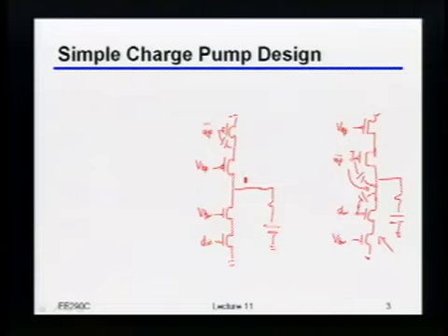The VGS keeps changing? Between what and what? Between the two cases. The up bar. Yeah, okay, so you're saying here we're changing the VGS of the current source device, whereas here we're changing just the VGS of the switch. Okay, that is true, although I don't think there's really a way around that because we have to turn things on and off. So somewhere something like a VGS is going to have to change.